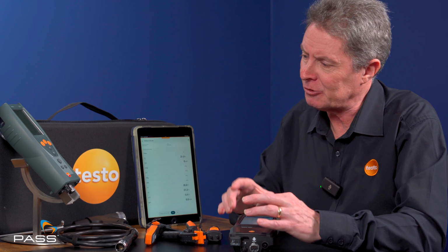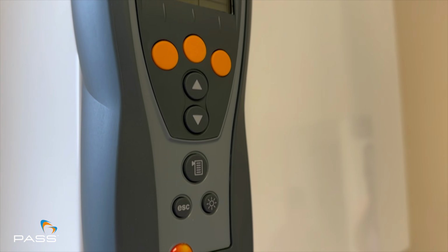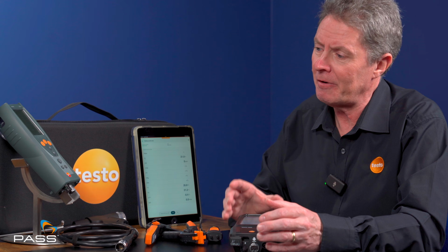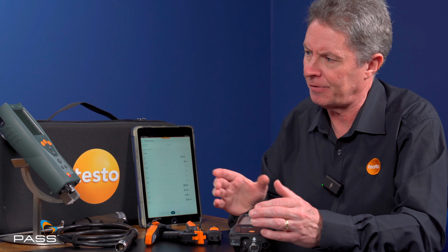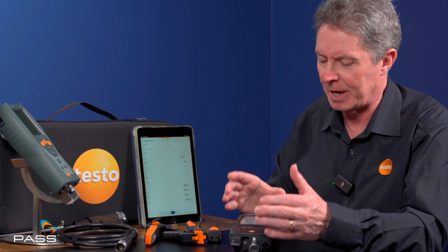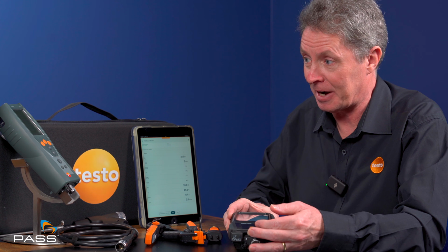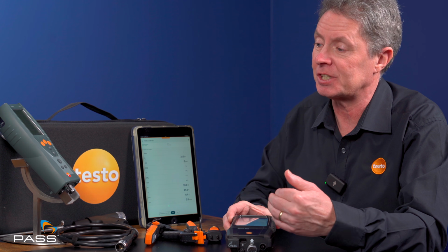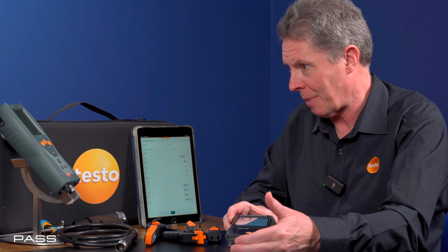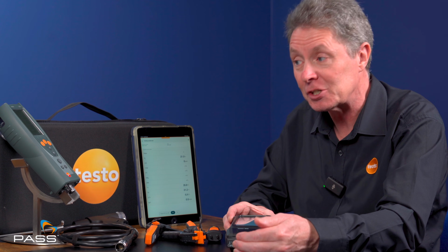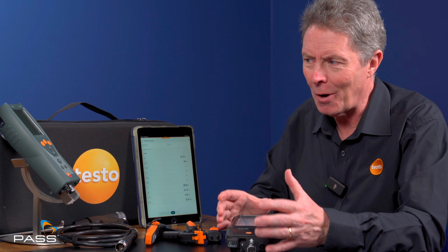But also the electrochemical cells are depleting as the analyzer is being used. We've seen people run up very large bills over the years where they've been using the incorrect analyzer for the application. The classic is people in the commercial world using a domestic-level analyzer and then hitting lots of CO spikes because it's not designed for that level of CO. Then having to send the instrument back, they're left without an instrument to use, potentially, and they've got a bill for replacing CO sensors. It's all about buying the right instrument.